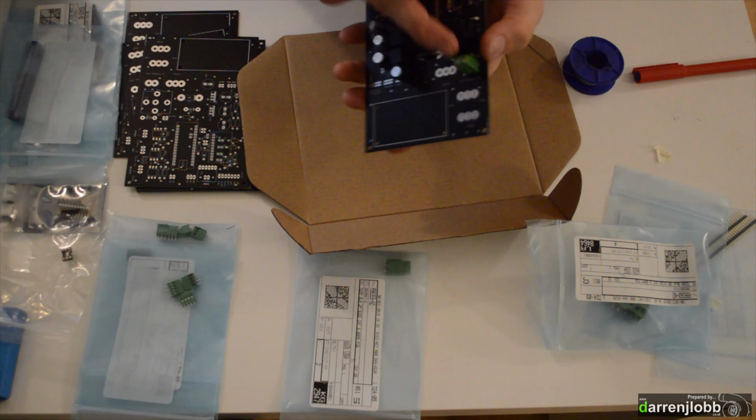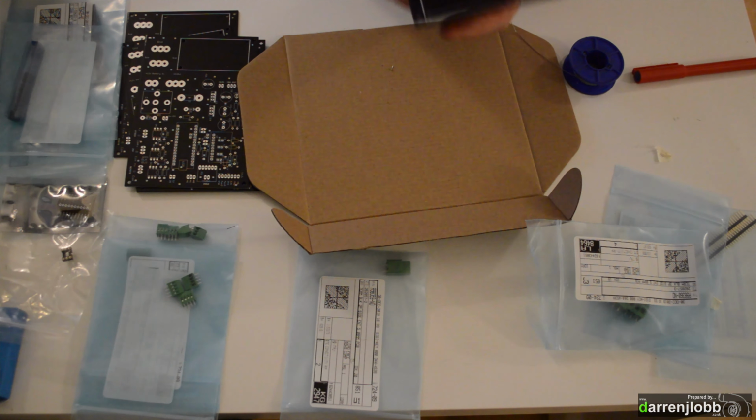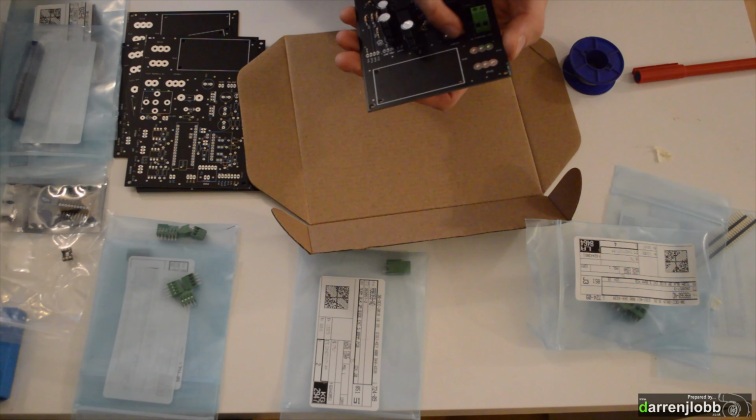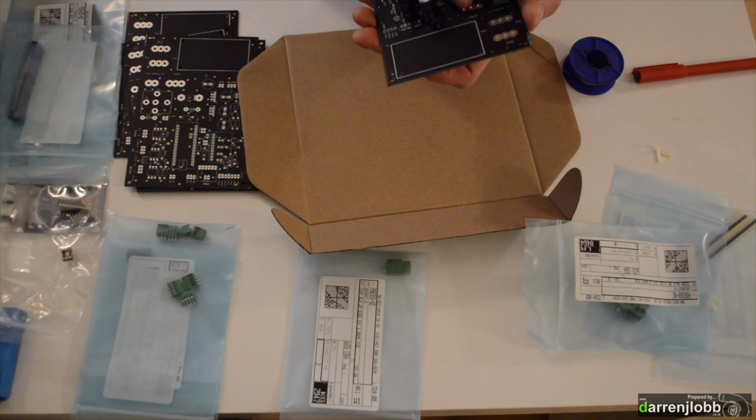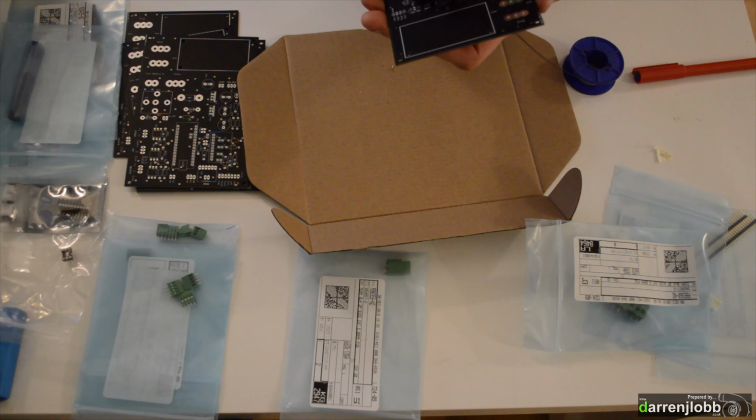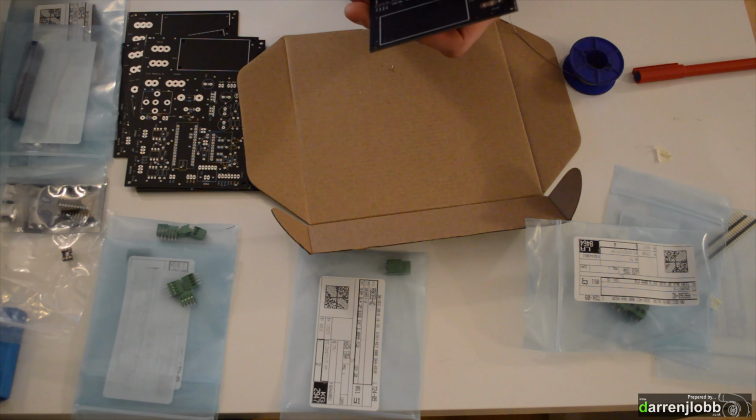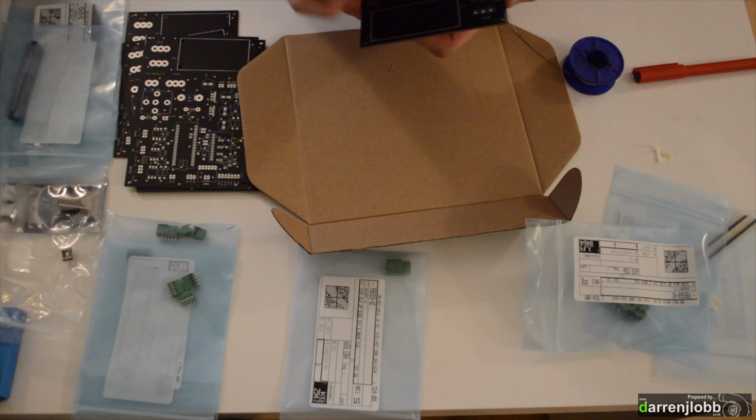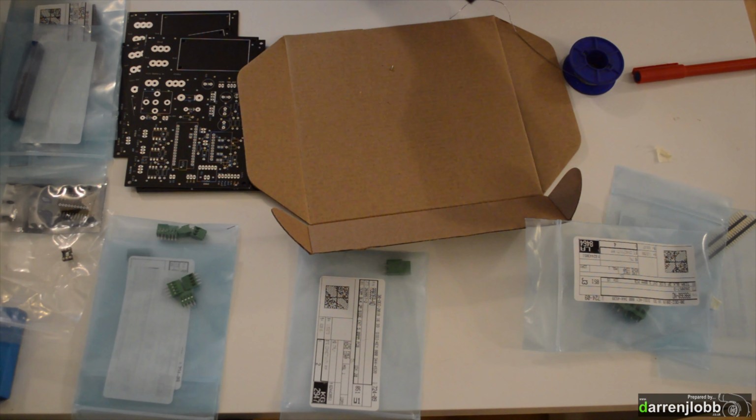That 2-pin one I've just put on is your 12 volt in, so that's before the relay, basically where you feed it from. Then we've got 12 volt out, which is switched power, so we can power other devices like the motor driver, etc. from that 3-pin terminal. And we've got a pair of ground terminals at the top here, both with 3-pin connectors on them.